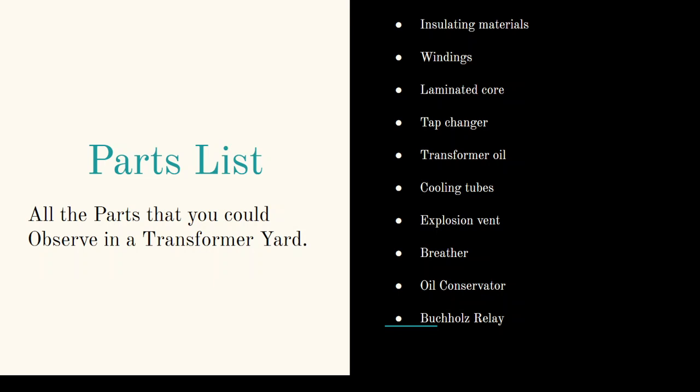Explosion vent. Explosions in transformers are possible. We don't want the entire transformer breaking up. In that case, you have a small vent, which is the weakest part of your transformer, that explodes to say that there's a fault inside the transformer.